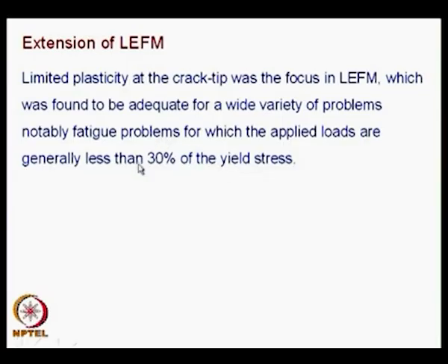So, you are talking of structures which are loaded far below the yield stress, and you are confining your attention to high strength alloys, and LEFM was sufficient. And this was possible because you had only limited plasticity at the crack tip.